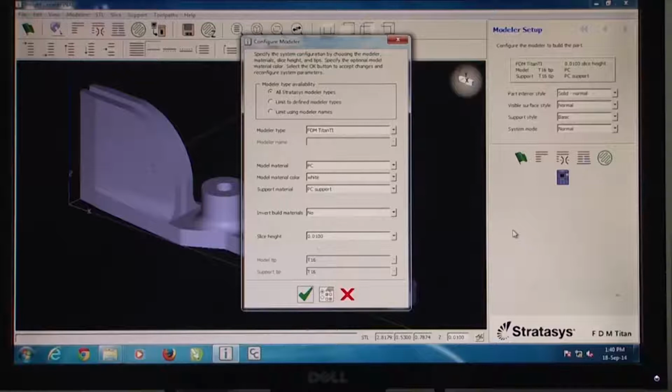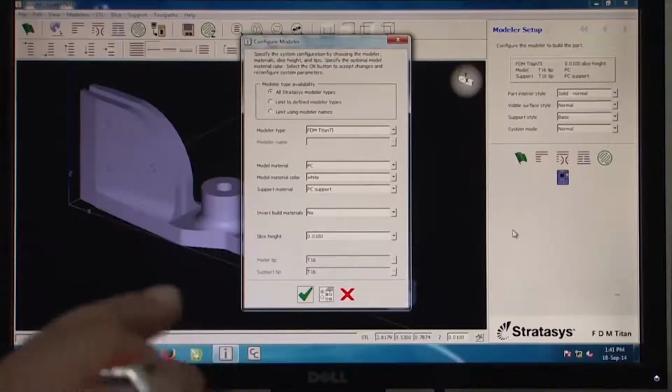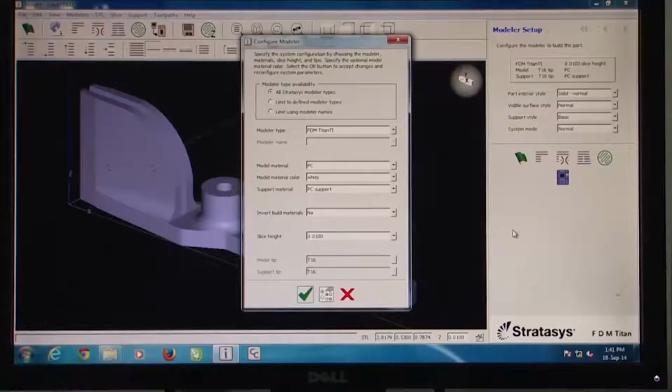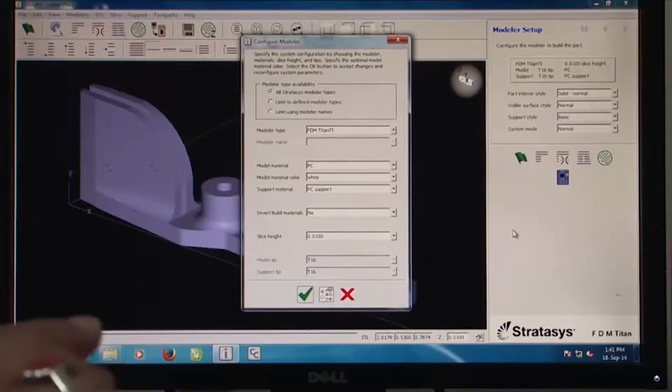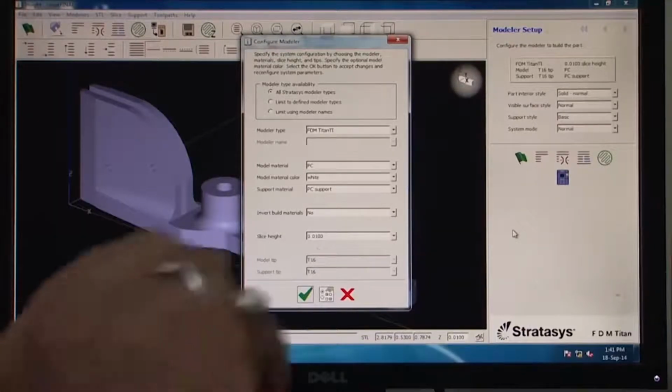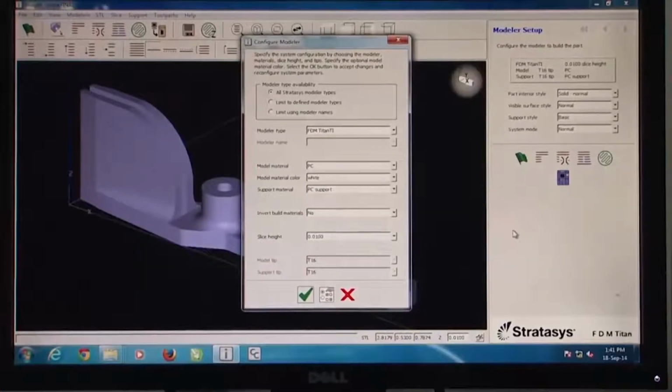We have to remember that there are about 4 nozzles in this system which has been delivered or specified by the manufacturer, and they are classified as 4 different types: T10, T12, T16 and T20. Each of them has a different orifice diameter, because ultimately if your slice height has to be more, naturally the dispensing rate also has to be more for the tool to actually be able to carve the object out.